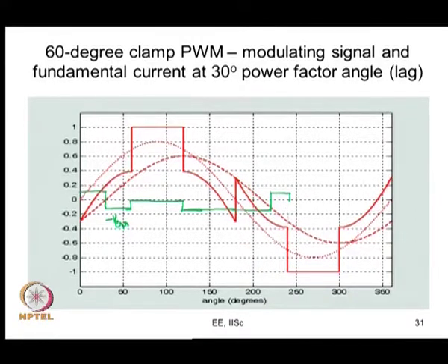Now, here it is clamped, the phase is clamped, and therefore, the error is 0. Once again it goes like this. So, this is plus V error, here also plus V error, and what is this V error? VDC TD divided by 2 TS, same as before, but the wave shape is different.